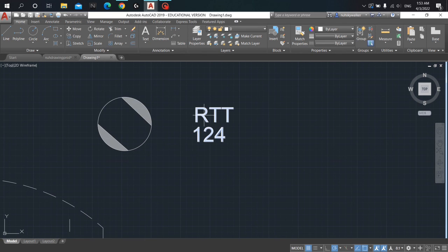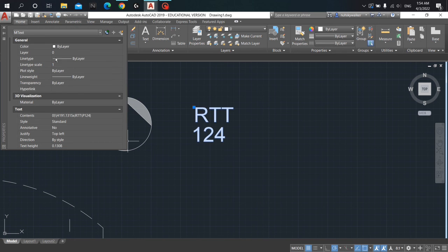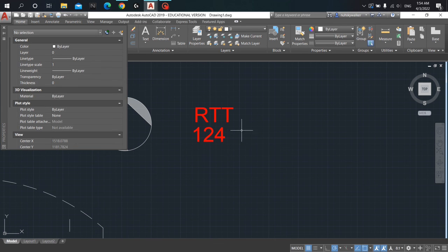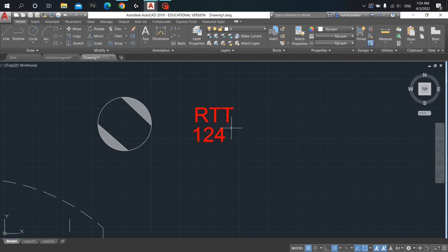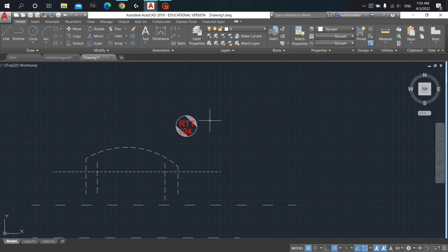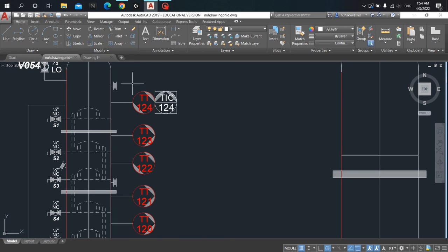So just left click on it and right click on it, go to properties, choose this one, change the code, change it to rate, then click on close. And then as per usual, you select it first and then click on move. Base point maybe at the center, so that you'll be able to put it somewhere here. Yep. That is how I created this particular thing.